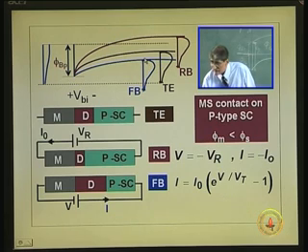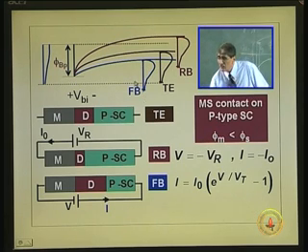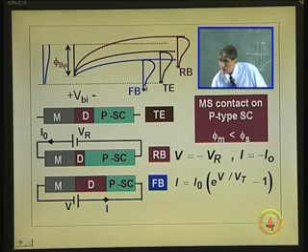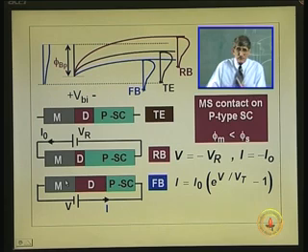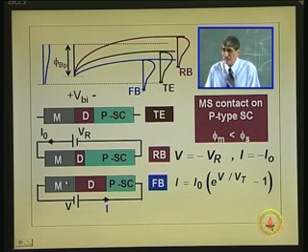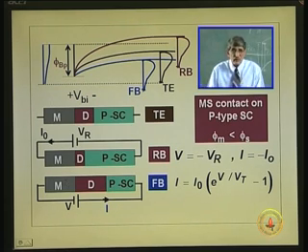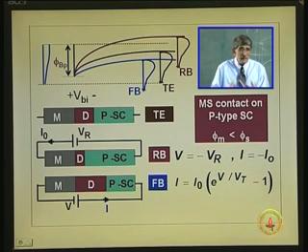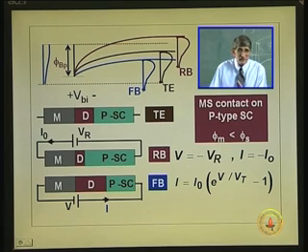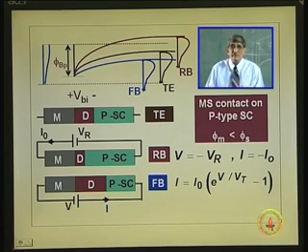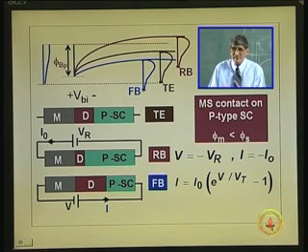Now, when you forward bias, this is pulled down here. So, you have more of these holes which can cross from here to here compared to this. So, when you forward bias, you have got hole current from semiconductor to metal. Equation is the same thing. We had so much detailed discussion on n type and I gave a glimpse of the p type, you can actually sit down and work it out in detail. The idea is that one thing you remember, reverse bias depletion layer widens, forward bias depletion layer narrows, okay. Reverse bias barrier height increases on the semiconductor, forward bias the barrier height falls, okay.